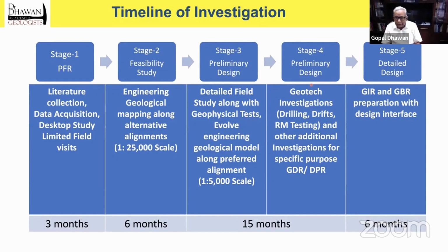And in the third stage, we go for geotechnical investigations: drilling, drifting, rock mechanic testing, and other special tests which may be required depending upon the geology of the project. And now at this stage, we should have enough data to synthesize a GDR, the Geotechnical Data Report, and the DPR. This is the conventional document in India which is required for seeking approval of the regulators.